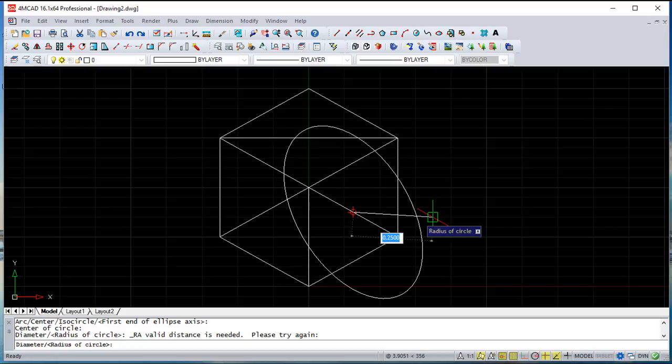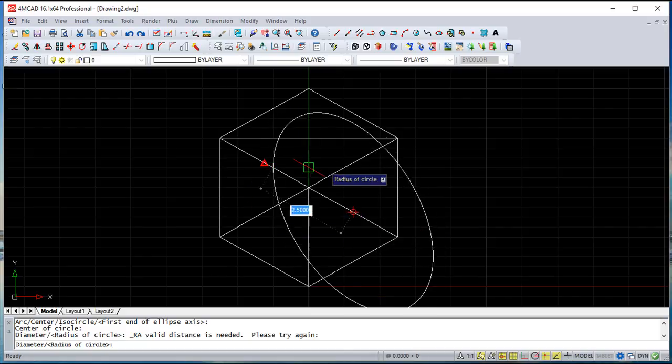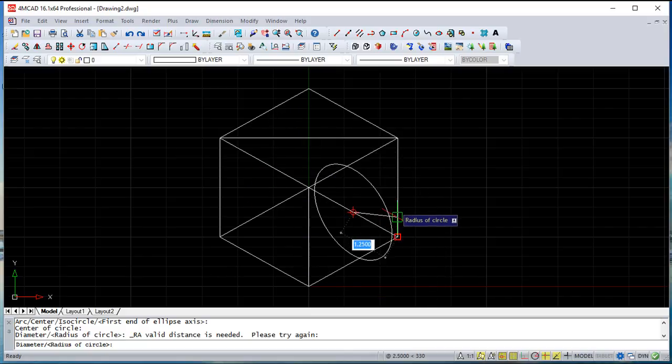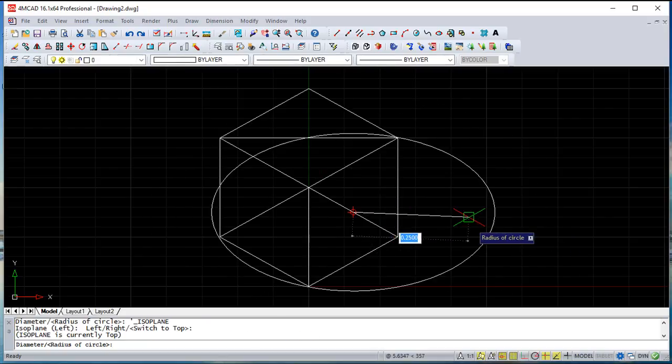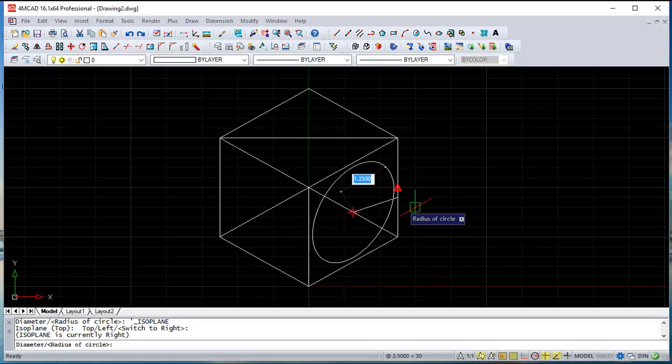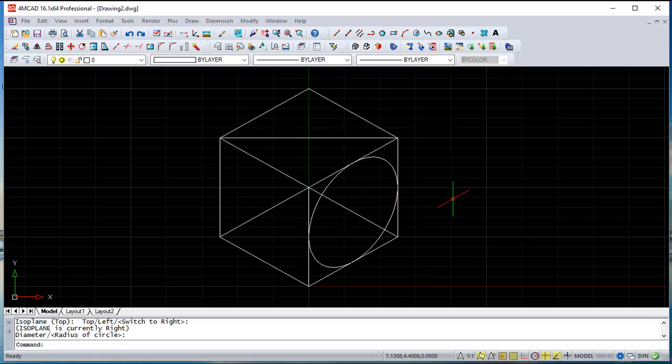And you can change the position of this isocircle because it can simulate one of the faces of the cube through the function F5. So now it is top. Now it is on this face, okay, and it is drawn. I will take this line out so that you can see better. So you see, and I could do the same for the other faces. Let's try one more, the top one.